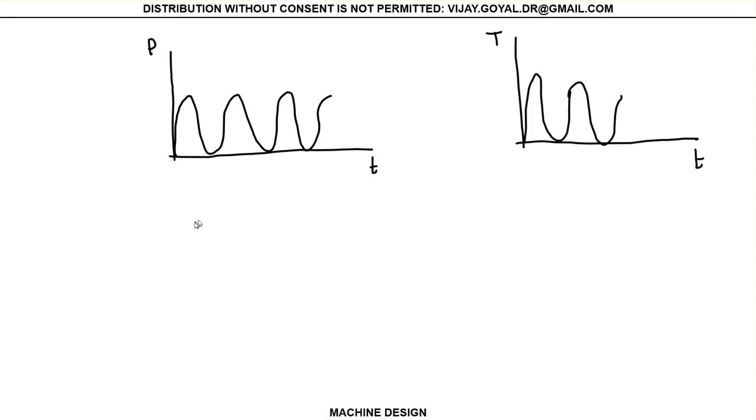Before we start the problem, we know it's giving me the maximum load because it says that it's fluctuating between a load here and a load there. But remember, the loads that we have to use are the design factor times the load that's given. So this is 1.5 times 50,000, and that will give me 75,000.